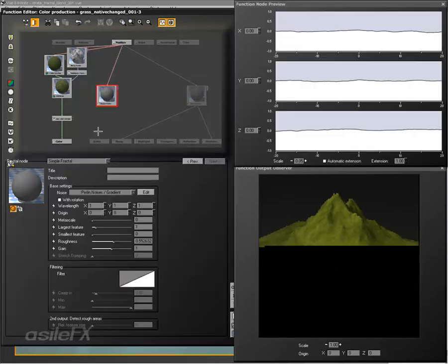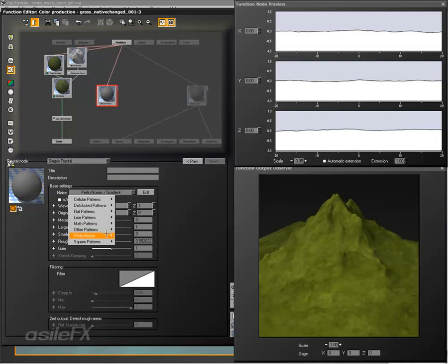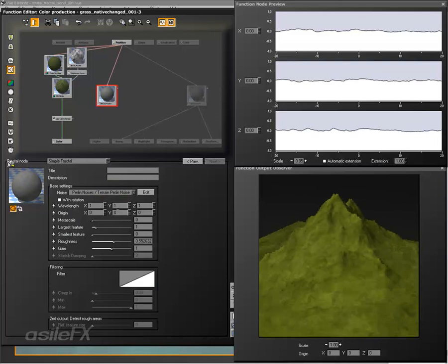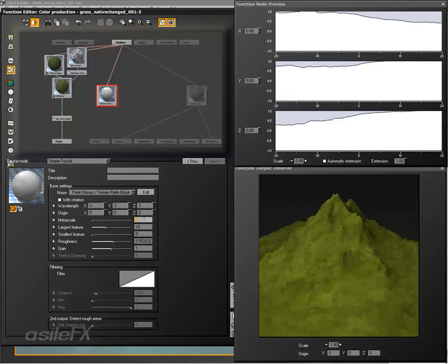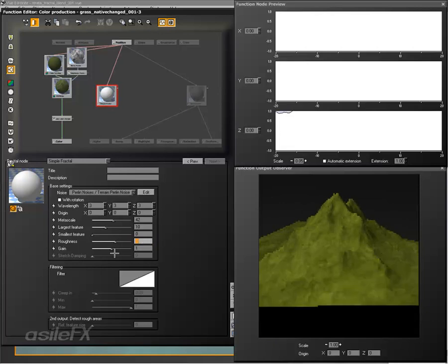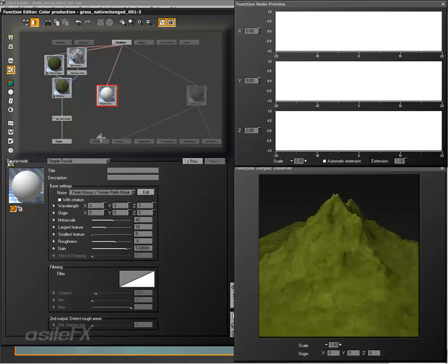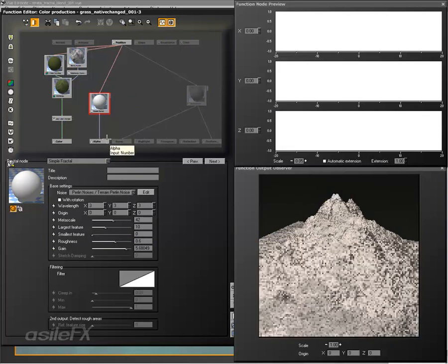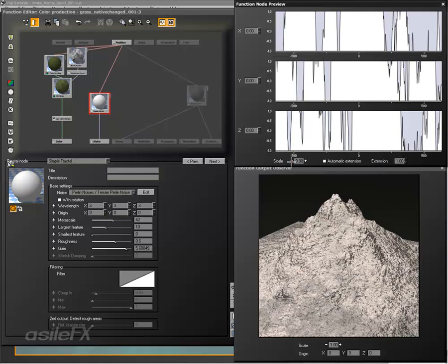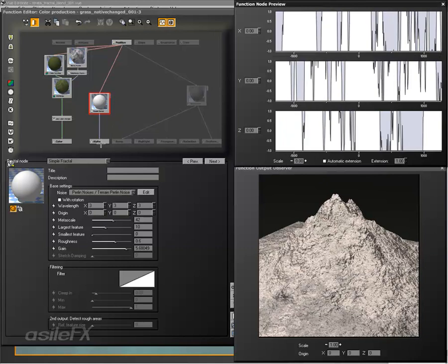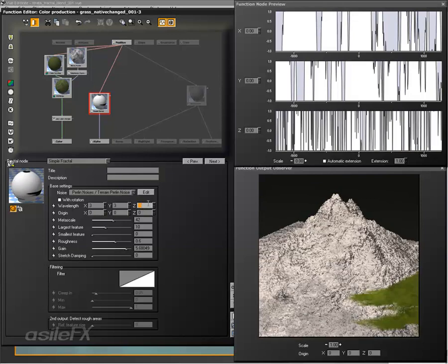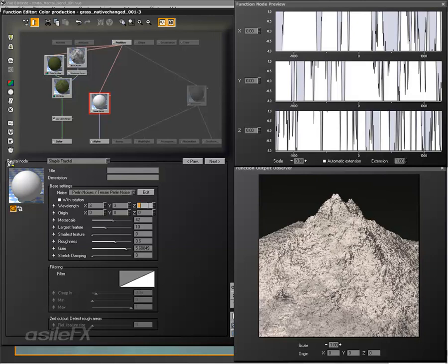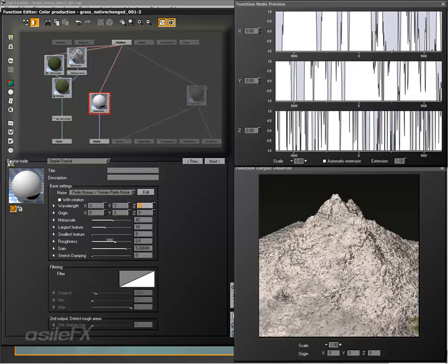So I'm going to use a fractal. Using a simple fractal, use Perlin noise, terrain Perlin noise. Set the wavelength to 3, largest feature to 10, metascale 42. Decrease roughness to 0.6, increase gain. Connect the alpha to the altitude, and then take a look as well and see the output. Also going to take that wavelength. Let's just use a value of 0.5 instead of 3.